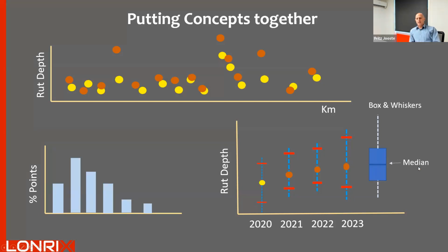But generally, as a standard, the box and whiskers plot would have a line indicating the median, and then you'd have the 75th percentile and the 25th percentile. The height of this plot would then be your interquartile range, because this 25th percentile is one quartile and that's the other quartile, and this is the range between the quartiles. Now in JunoViewer, if you select this bar to be the 75th and the 25th percentile, you basically have the equivalent of a box and whiskers plot.